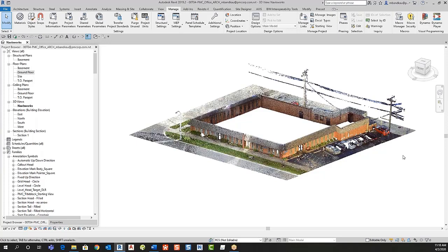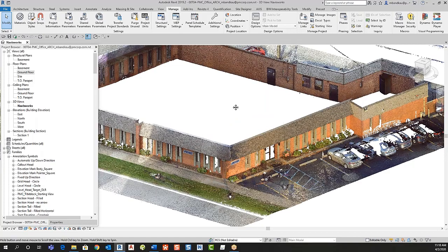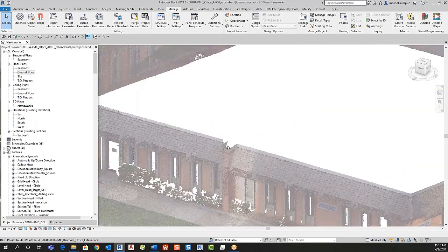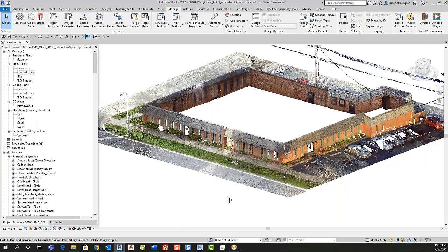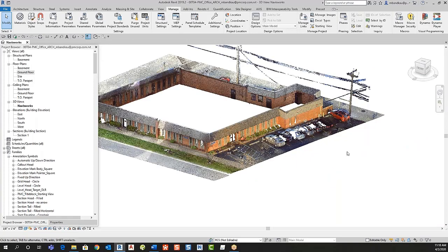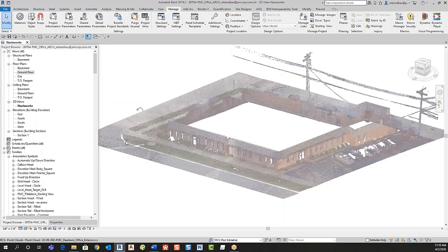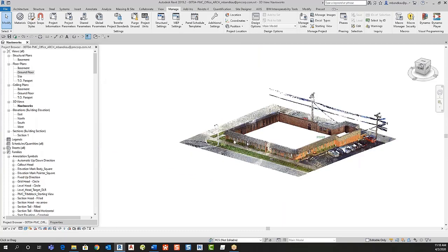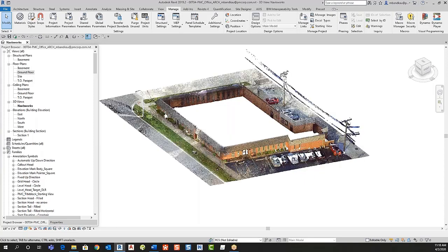parapet here. Now we knew that we were going to do a drone flight over this, so we did not need anything above that roof parapet that may have been captured in this exterior scan. So using Autodesk Recap, we're able to remove certain points and isolate the scope of the project. So we really didn't need anything beyond this box. And then RCS can be exported from Recap and brought into Revit, which is what I will get into now.